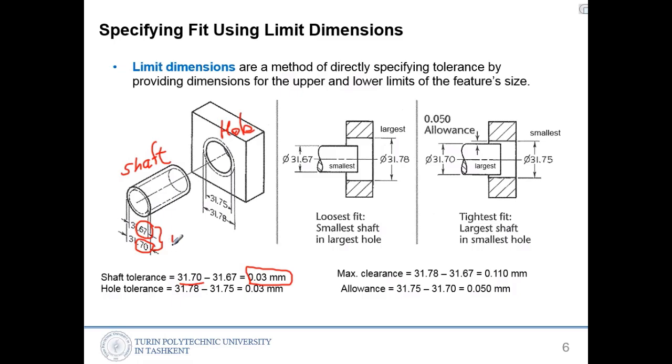We call this one IT grade also. And the hole tolerance: from the biggest one we're subtracting the smallest one, 31.78 minus 31.75, we got again this kind of value. So that's the hole tolerance.